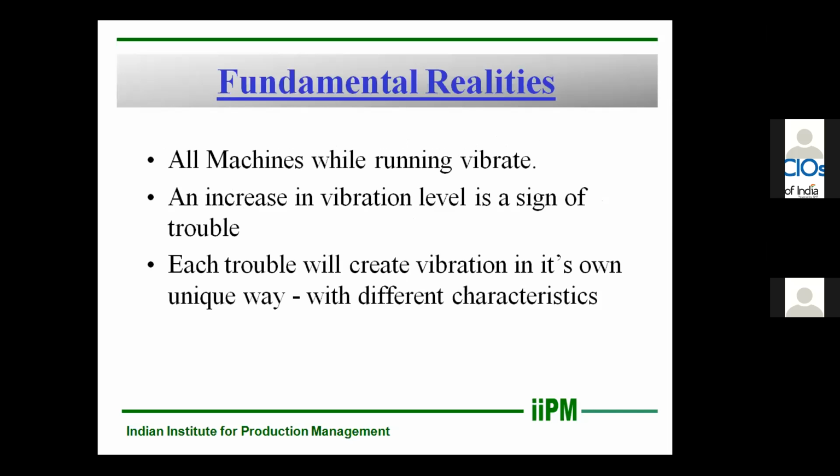So what are the fundamental realities? All machines while running will vibrate. It is a general phenomenon. If a machine is running, it will vibrate, whether low or high depending upon the application. But when the vibration level increases, it has some trouble. Each trouble has its own pattern, its own signature. Not every type of problem will have the same pattern. So as an analyst, we need to study that pattern and diagnose.